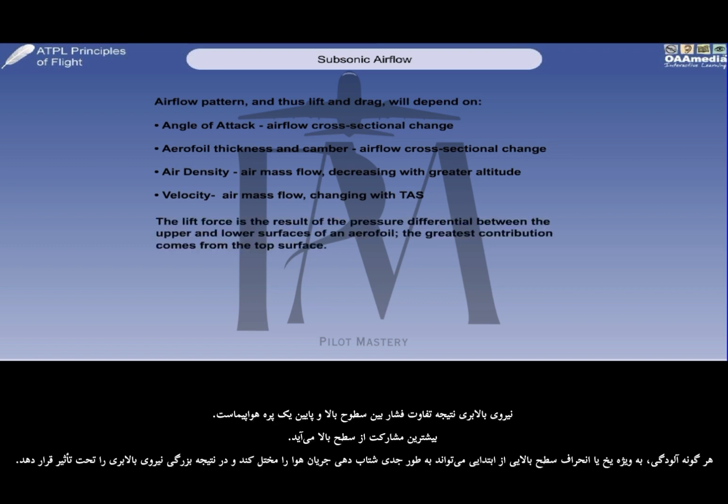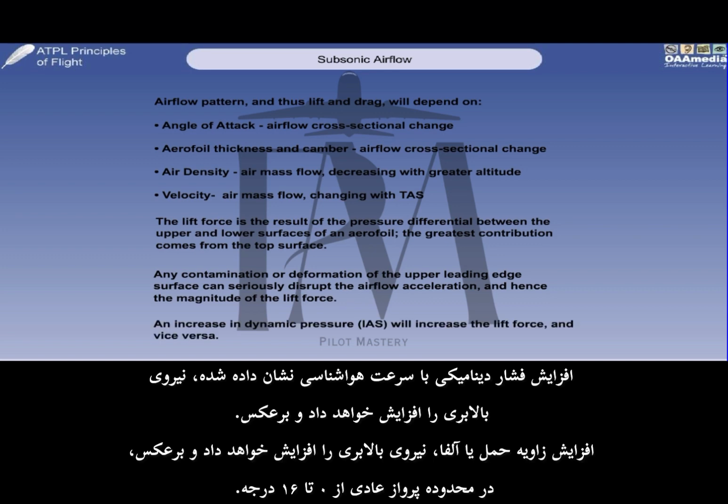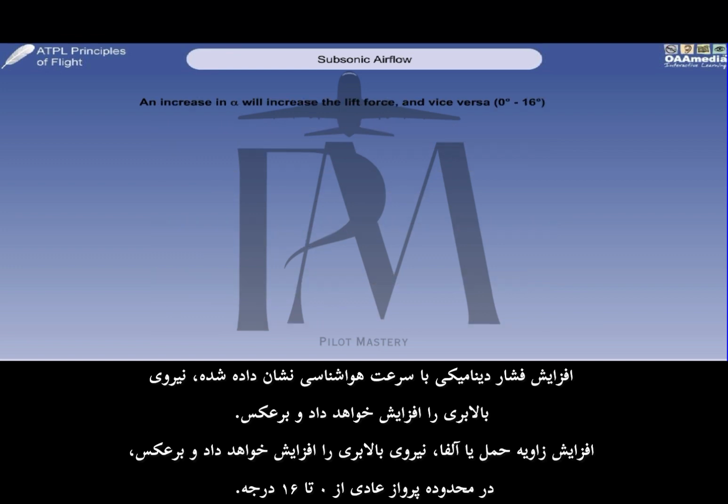The lift force is the result of the pressure differential between the upper and lower surfaces of an aerofoil. The greatest contribution comes from the top surface. Any contamination, particularly ice, or deformation of the upper leading edge surface can seriously disrupt the airflow acceleration, and hence the magnitude of the lift force. An increase in dynamic pressure with indicated airspeed will increase the lift force, and vice versa. An increase in angle of attack, alpha, will increase the lift force, and vice versa, over the normal flight range of 0 to 16 degrees.